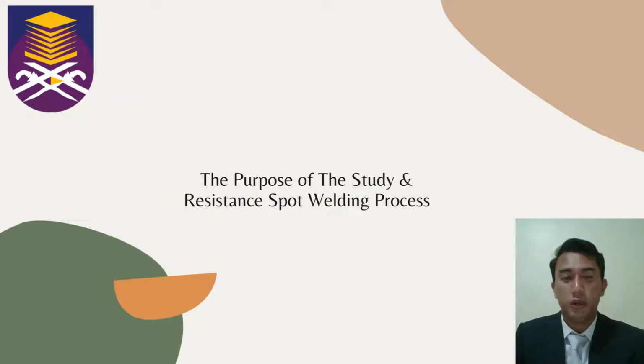The introduction of resistance spot welding. It is a process of joining two metal sheets which is commonly used in our automotive industry. The advantages of resistance spot welding are that it is fast, well maintained, and easily automated. Other advantages are low cost, efficient, safe due to no sparks created, the joint is strong, and no special personnel are required to operate. The important parts of using resistance spot welding are the selection of the material used and the design of the product.